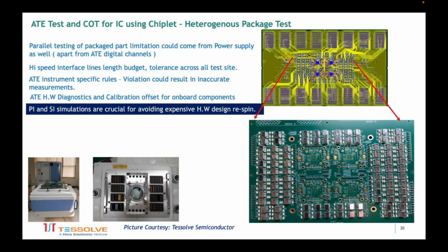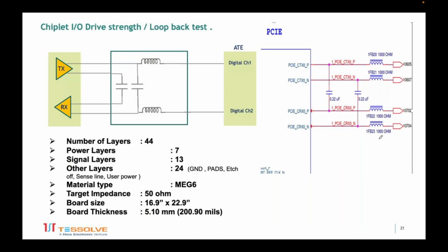I can quote some examples here. Before that, let me talk about one thing, the loopback. For example, we may put a capacitive coupled loopback. In the event that you also want to do some DC parametric, we can look at an inductor kind of thing. So it will behave like a bias in the RF world. So you could do some DC measurement and bring it and test.